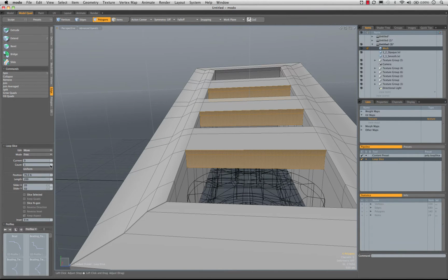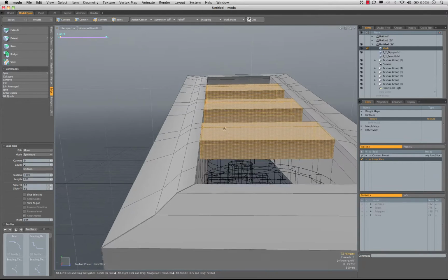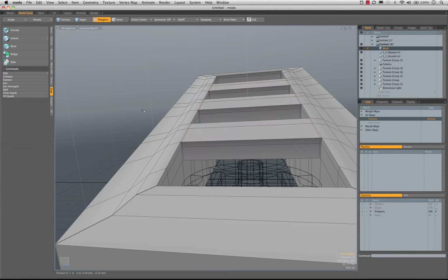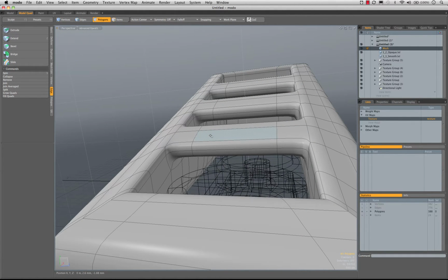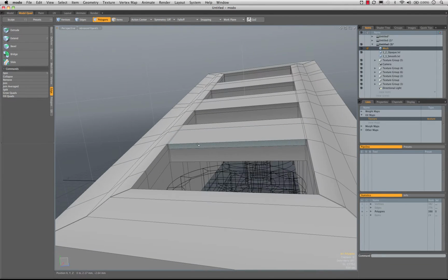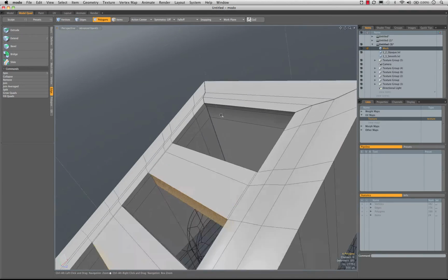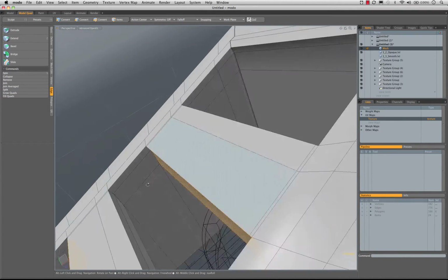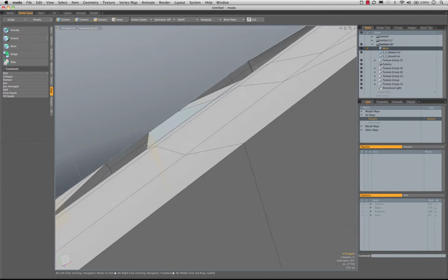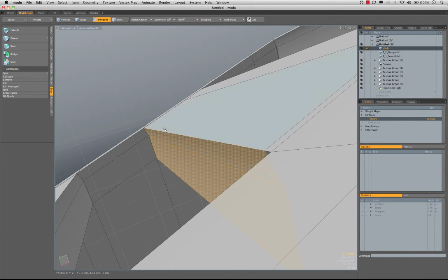So I'm going to run loop slice to in symmetry, and I'm going to take it almost all the way out. Not quite. I'll leave it at 1% instead of going to the 0.5, and then I'll have something that I can move down here. So let's go ahead and do that. And actually, sorry, take it back. Let's build these end caps here because we want these all to move down evenly. And then we want to flatten these pieces out too.